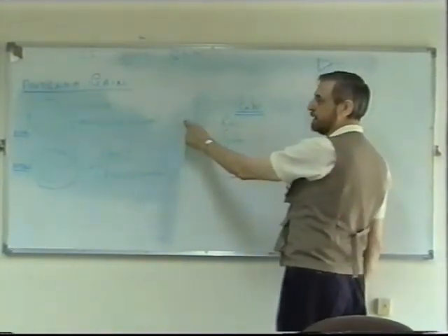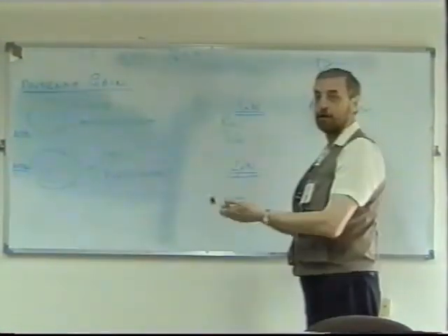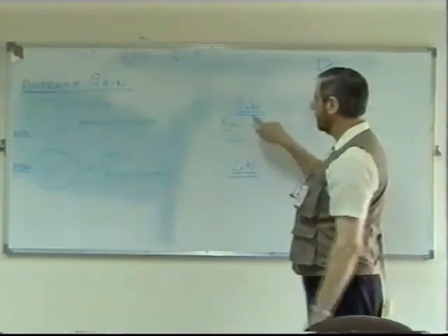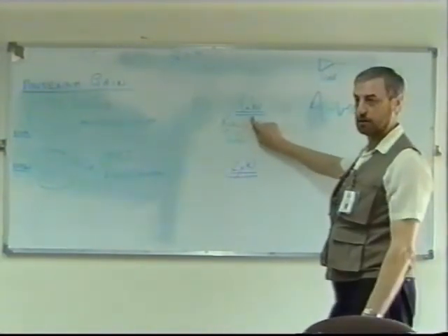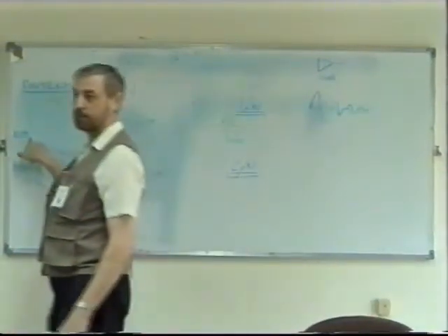Now, let's say in the previous example, I boost this power, I make the power bigger, so as to make this 2 microwatts, same as this. How much power would I need here? Yeah, 200 watts. So, using a different antenna, it appears to behave as though it's amplifying the signal. Instead of using 100, it's like an omnidirectional at 200 watts.